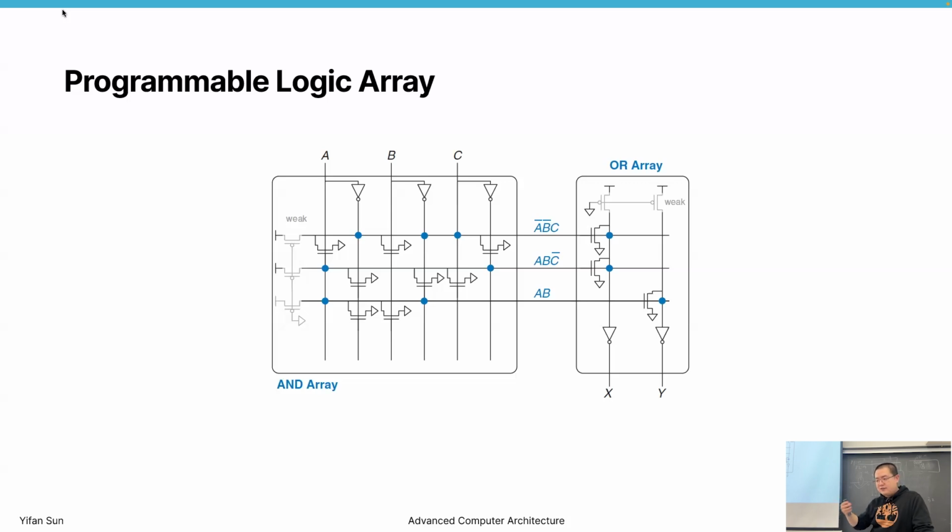So it has more and more different types of logic built in, but you can still write something like Verilog code and use the FPGA to generate this type of lookup table and produce the result for you. That is something people typically use before they produce a real chip. They implement the chip in Verilog code and burn it into the FPGA. Then the FPGA will run the same logic, and you can test whether the logic is correct or not.